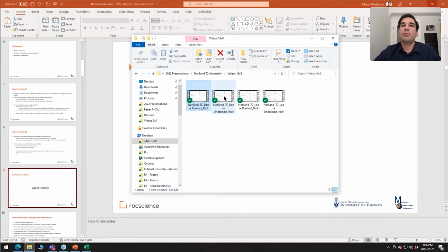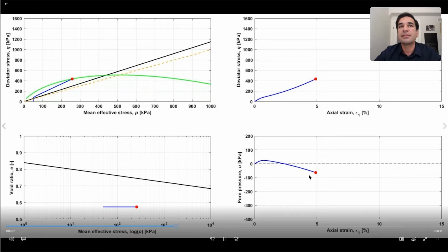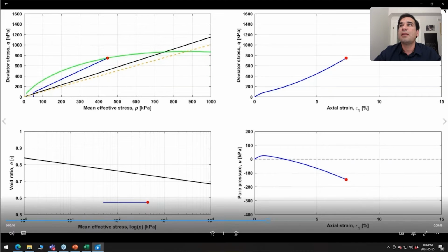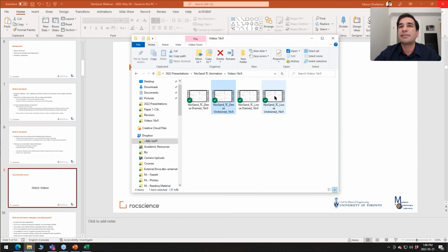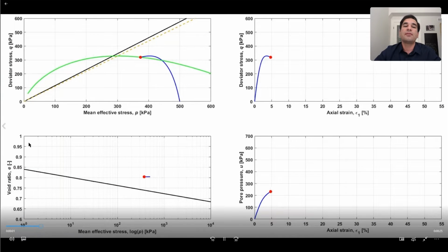And if we look at the dense undrained behavior again, this time we're looking at excess pore pressure. A bit of contraction at first, and then dilation is what you get, all with the exact same set of parameters and the same assumptions of the model. And finally, this is the one a lot of us are interested in.